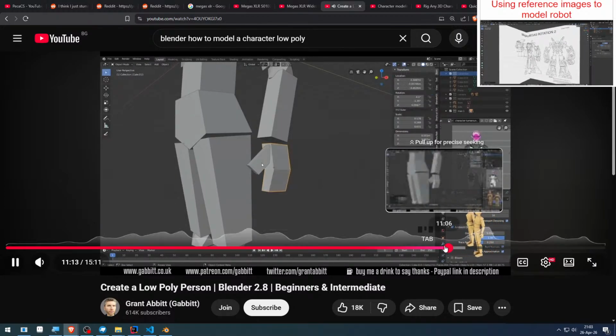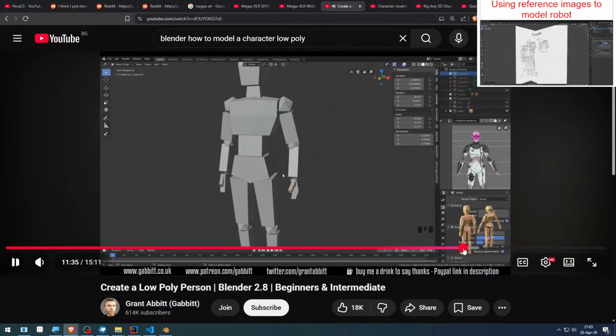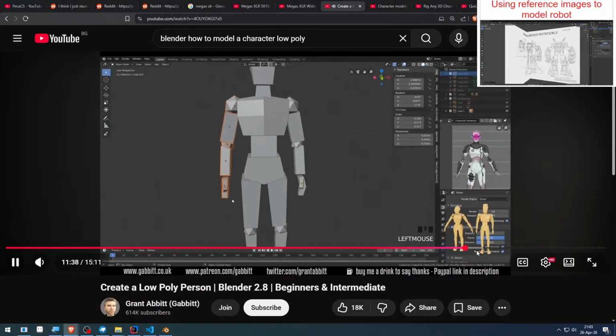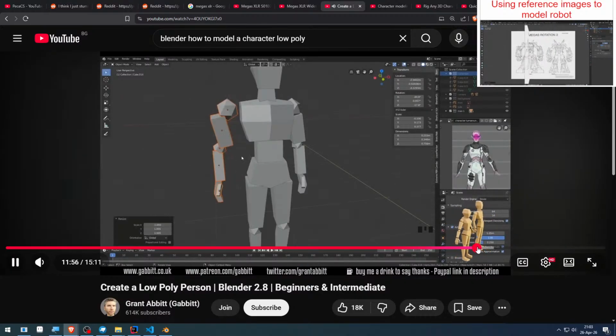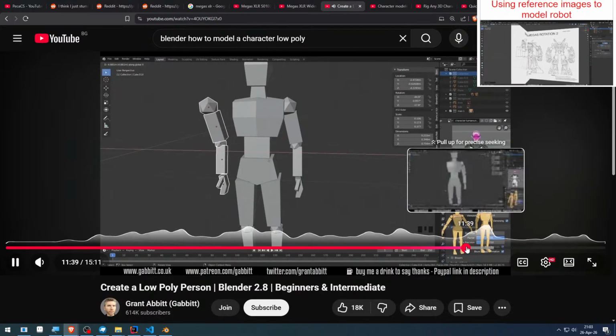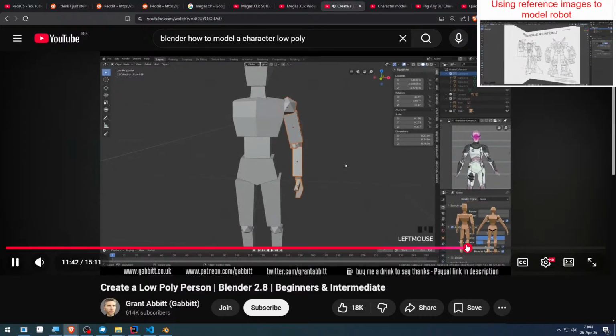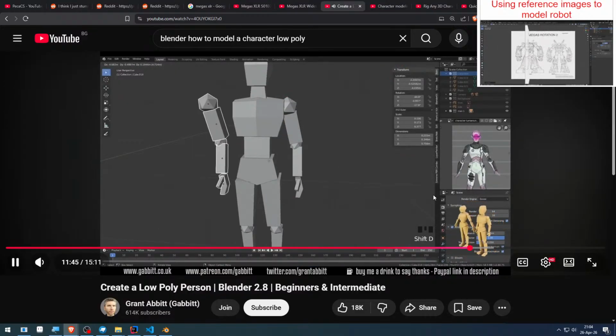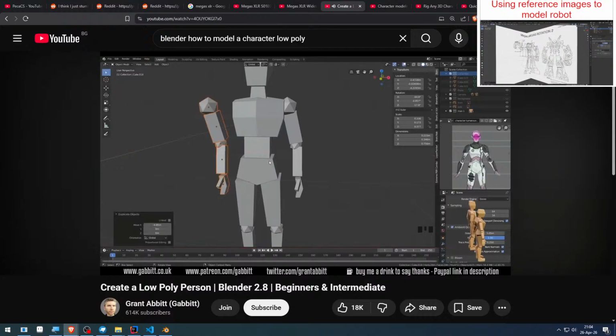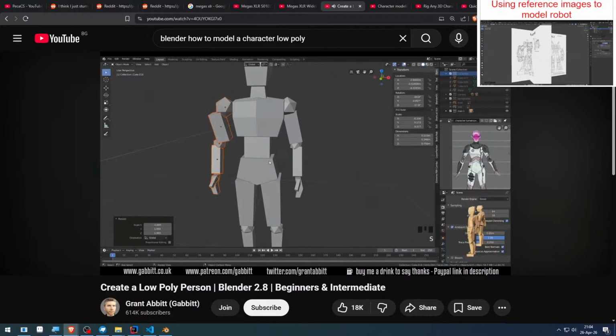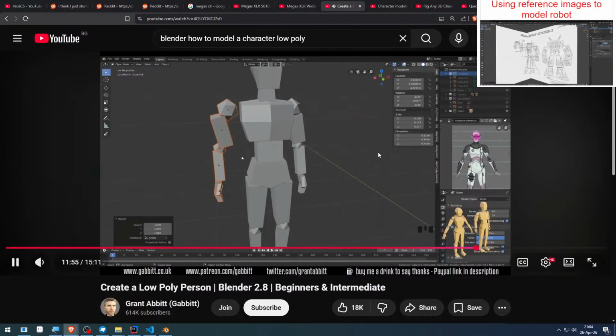So if I take this thumb for instance, let's click on that and go into edit mode with that, duplicating it across the other. So let's delete this side, selecting it all and delete, and select this side, and Shift D to duplicate, and bring it across the other side, so X to constrain to the X-axis, and then scale X -1. Now that hasn't quite worked, and there's a reason for that, and that's because it's using the local coordinates of these objects.